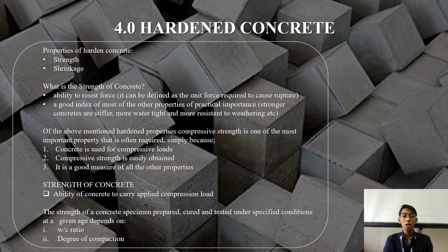Strength of concrete is the ability of concrete to carry applied compression load. The strength of concrete, prepared and tested under specified conditions at a given age, depends on the water cement ratio and degree of compaction.